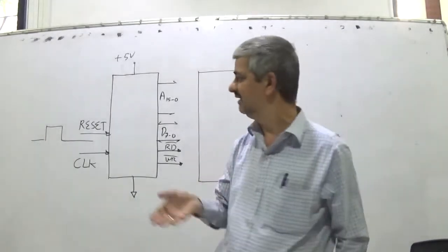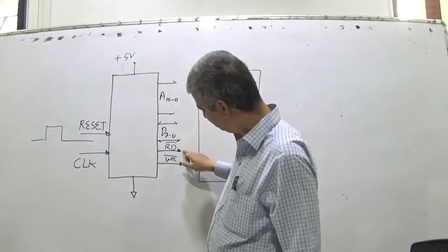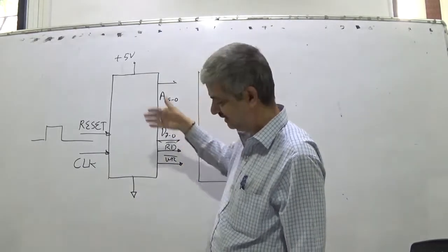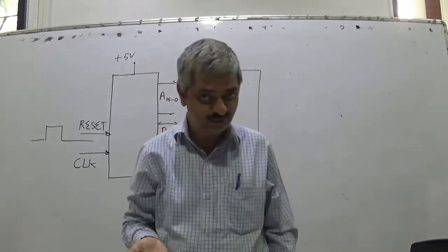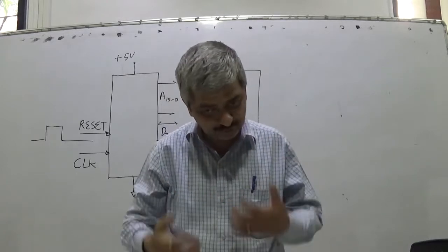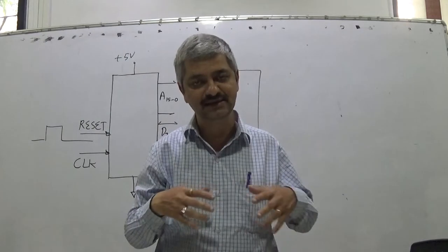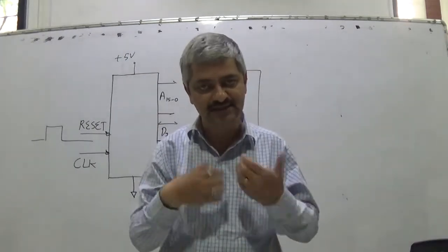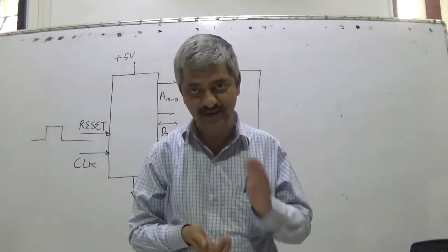In the reading operation, it puts something on the address lines, puts read bar low and takes data. So now, what can a microprocessor do? What it can do externally is very limited: either undergoing a read cycle or a write cycle.